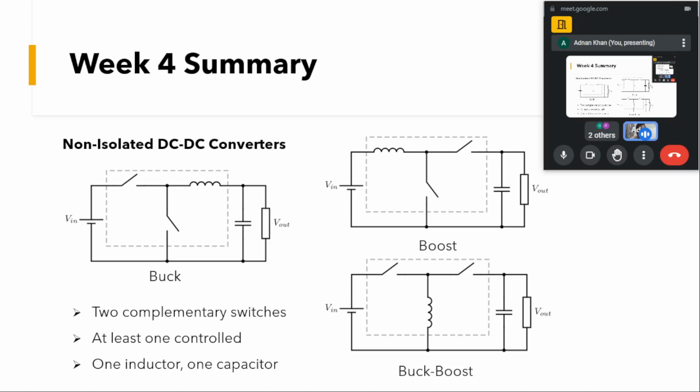At that moment, only a buck converter cannot give us that flexibility, and similarly the boost converter does not have the flexibility for both kinds of operation. There we'll use this topology where I am pointing the cursor, and this topology is known as the buck-boost topology.